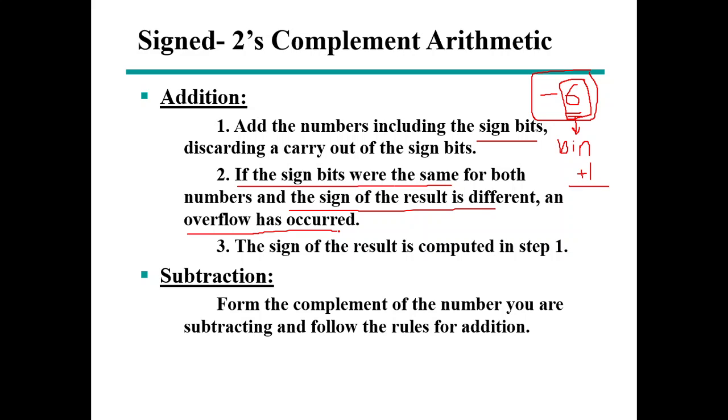For example, if you add two positive 8-bit numbers, their most significant bits must have been 0, but after addition the most significant bit of the result turned out to be 1. That means that the sum of the two numbers, the addend and augend, could not be specified in the bits that were reserved for the sum. So that's why the result has overflown into the sign bit.